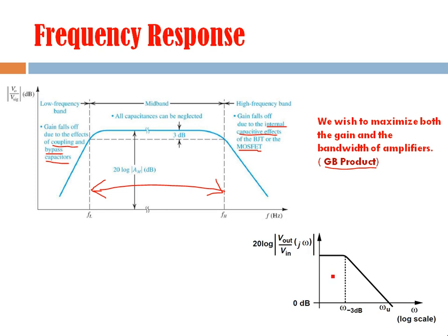So in case of differential amplifier or any direct coupled amplifier, we are concerned about this 3 decibel frequency, and this is our bandwidth actually, because starting from 0 to this frequency, gain remains constant, right? And the decrease in gain starts beyond this cutoff frequency.